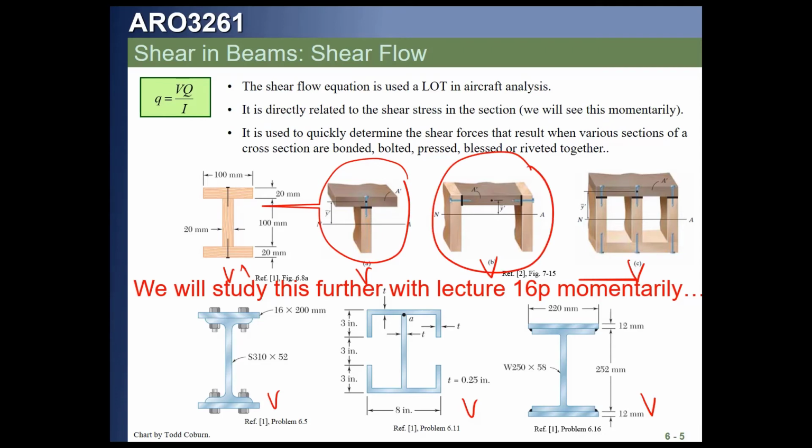We would then go and say, well, where do we want the shear flow? If we look at this beam, we've got an upper plank and it's attached to this next plank by this nail. So if we want to know the force per nail, moving from the centroid, which is somewhere about here, we're going to need to cut everything off away from the centroid through that plane. So if this is the centroid and this is the plane where we want to calculate our shear flow, we're going to cut everything that's away from the centroidal axis, and we're going to calculate the Q of that,